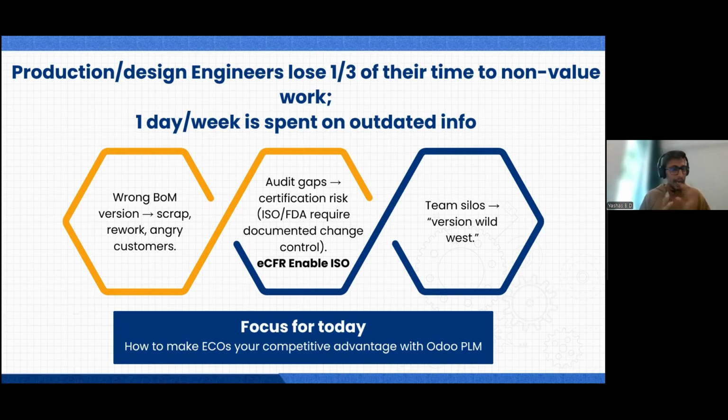So having wrong BoMs or changing the versions of the bill of materials without any proper documentation will eventually end up generating scrap, or us doing the reworks again and again. And sometimes, even with established products, an unaudited change in the bill of material can end up causing product defects which will be faced by the customer, because of which there will be a lot of complaints, a lot of rollbacks, and then an unsatisfied customer.